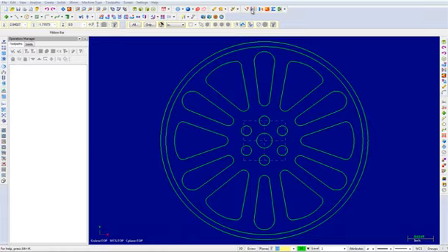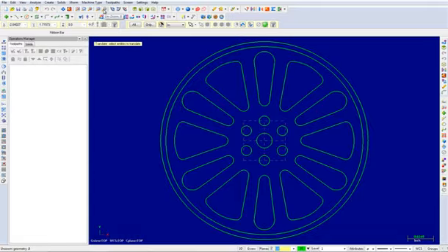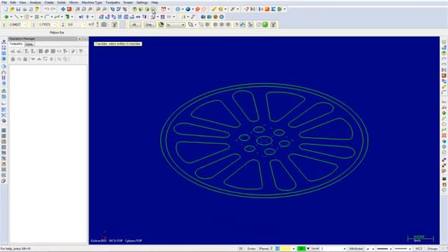Finally, we will use the command Xform Translate. In this step, you will learn how to translate entities to a different Z depth. This geometry will be used when creating a toolpath from the bottom of the part. That being said, select the Xform Translate command as shown. Now choose the isometric view from the toolbars. From here, select the 2 outer circles as shown. Once complete, choose the End Selection button from the ribbon bar.